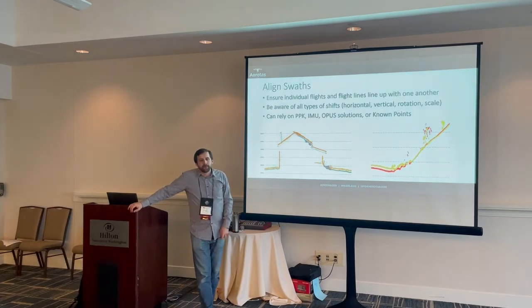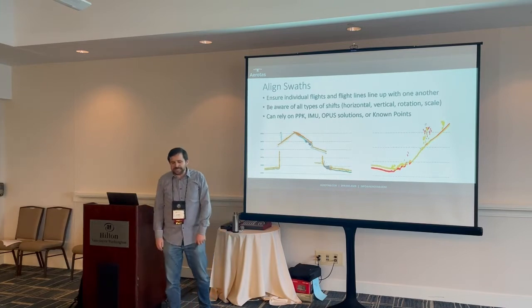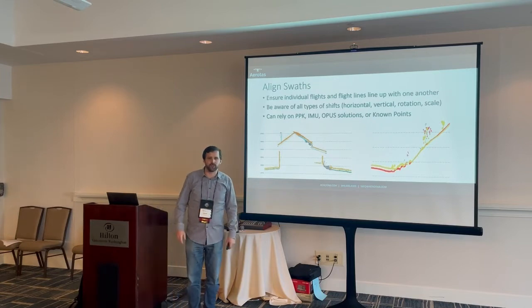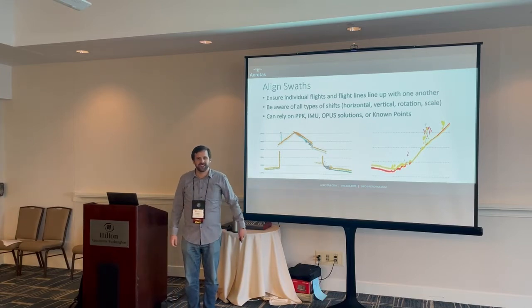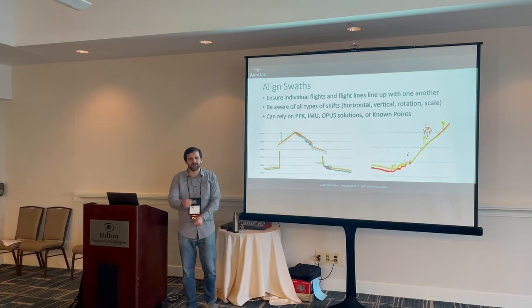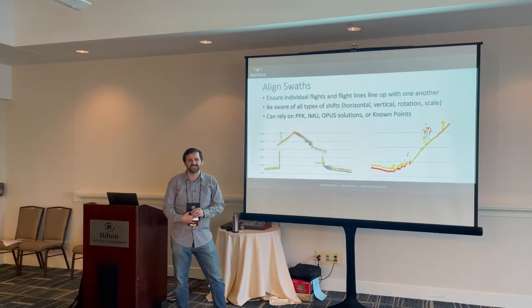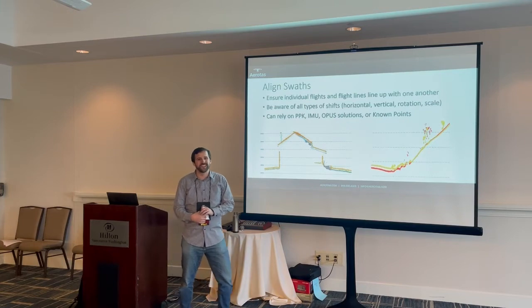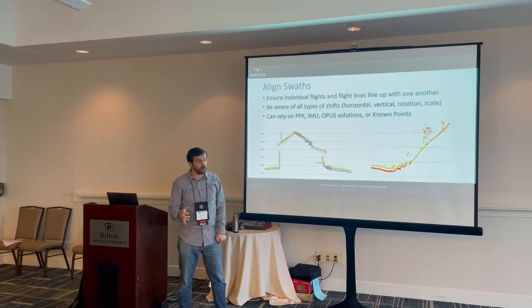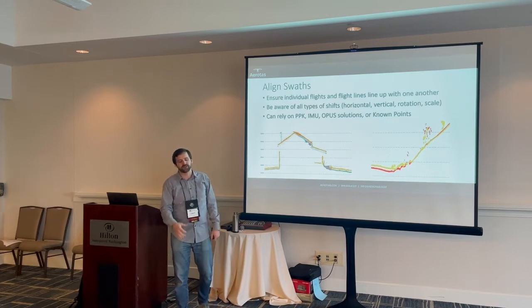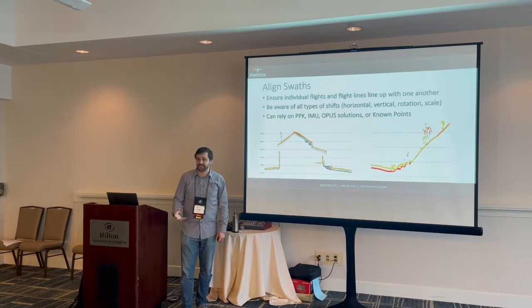So does the M300 L1 package come with the local base station? It does, yep. It comes with DJI's D-RTK 2 base station, which is very good at one thing and one thing only, which is streaming corrections to DJI drones. They try and put other stuff on their website like, oh, you can use it as a handheld surveyor. Don't. The software for that is terrible. I don't trust their leveling bubbles. I don't trust that the phase center of their antenna is perfect. But it is super great and reliable for streaming corrections so that the M300's LiDAR system is extremely precise.